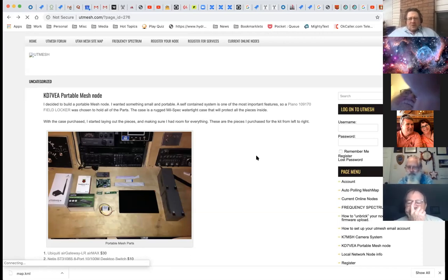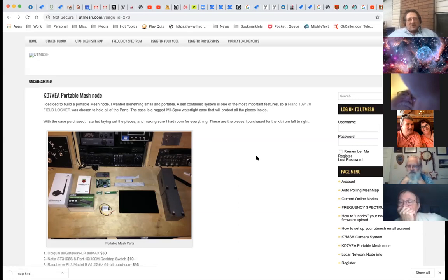What you'd do is set up the node at the hospital. So you'd have one node that is talking to Lake Mountain, for example, on that point-to-point type link. One that's talking to whatever you were looking at up in North Salt Lake, and then you would have one or two, or three, of those sector antennas that's kind of providing a general connection to anybody around, right? And so at home you would have maybe a Yagi antenna or one of those wire mesh directional antennas, and you would just point that at the hospital and tie into whichever node is pointing in your direction. And then once you can see that node, you're on the network and you can see everything on the network.